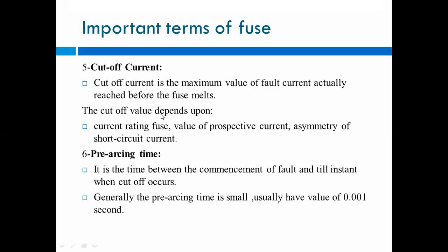Then pre-arcing time. It is the time between the commencement of the fault until the instant when cutoff occurs. If the fault has occurred and that conductor gets cut, disconnected or melted, up to that point is nothing but the pre-arcing time.